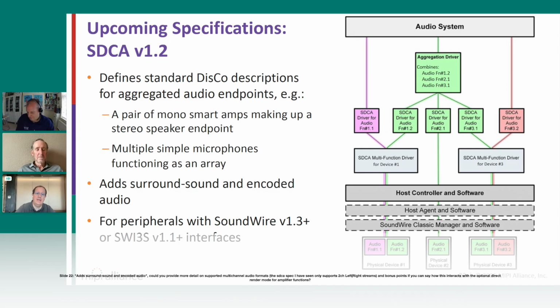The difference between that and Render Direct is that Render Direct talks about the equipment side of the channel space. So if you've got 4 amps in a tablet or a laptop, maybe they're top left, top right, bottom left, bottom right. Maybe you've got a subwoofer or center channel if it's a fancy laptop. The use of Render Direct is to let the host processor, like the SOC DSP, address each of those transducers directly, knowing its position in the equipment.